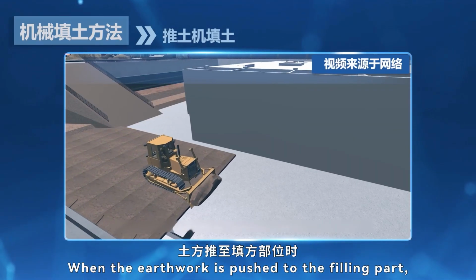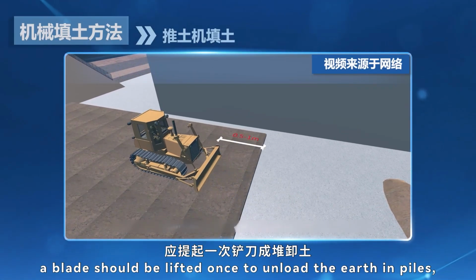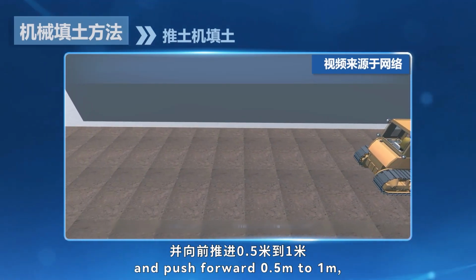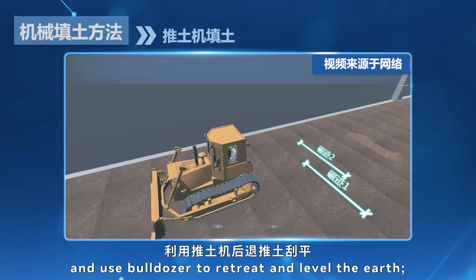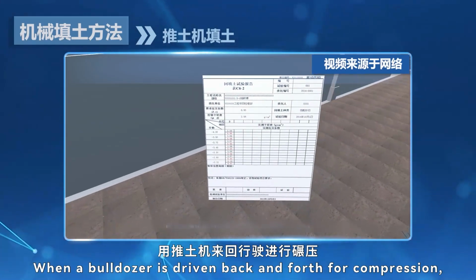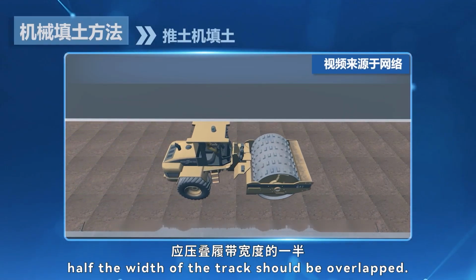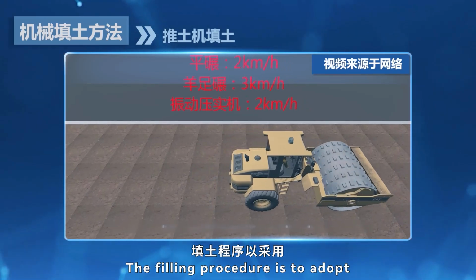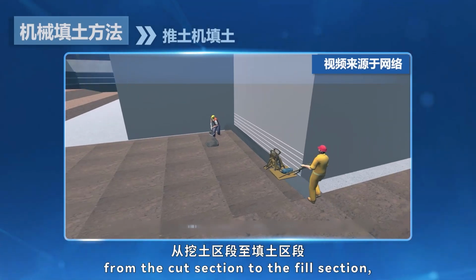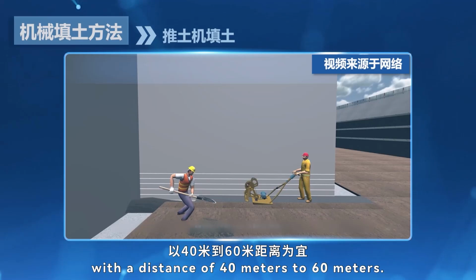When the earthwork is pushed to the filling part, the blade should be lifted once to unload the earth in piles and push forward 0.5 meters to 1 meter, and use the bulldozer to retreat and level the earth. When a bulldozer is driven back and forth for compression, half the width of the track should be overlapped. The filling procedure is to adopt the longitudinal paving sequence from the cut section to the fill section with a distance of 40 meters to 60 meters.